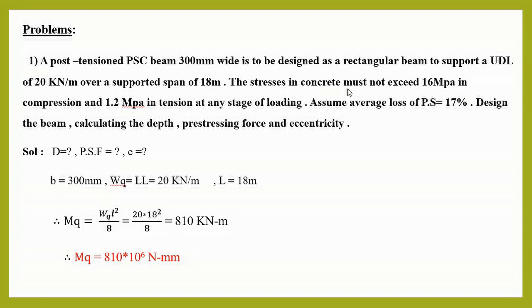The stresses in concrete must not exceed 16 MPa in compression and 1.2 MPa in tension at any stage of loading. Assume average loss of pre-stress is 17%. Design the beam, calculate the depth, pre-stressing force and eccentricity.